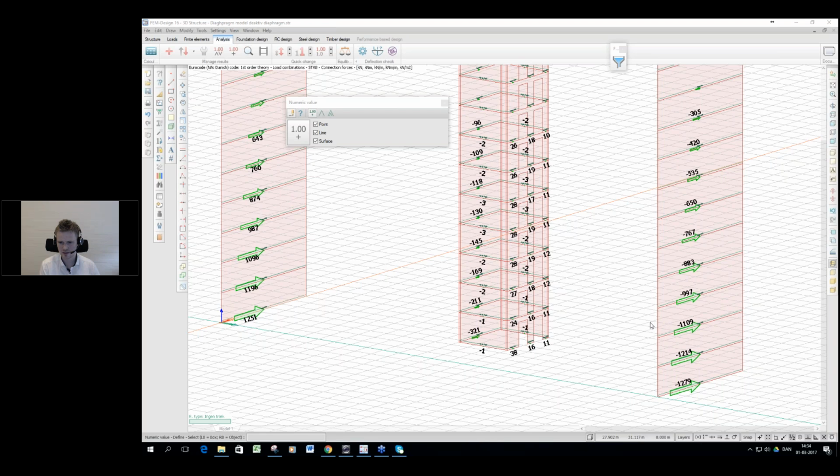For your example now, with the not so steep slab, is not the analysis without diaphragm more correct, since the slab is not infinite stiff? Yes, but that's religion here. As long as you have equilibrium, you can always say, okay, if the horizontal load distribution you get from the normal analysis, if your structure is stable, there's no need for you to start with rigid diaphragm.